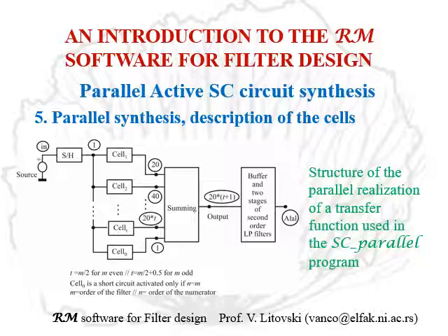In that way, a rather good selectivity is obtained of 24 decibels per octave as asymptotic attenuation, eliminating all higher frequencies related to the switching and sampling.